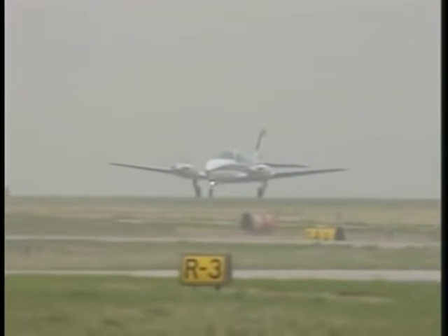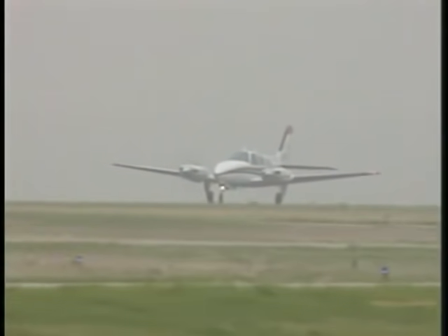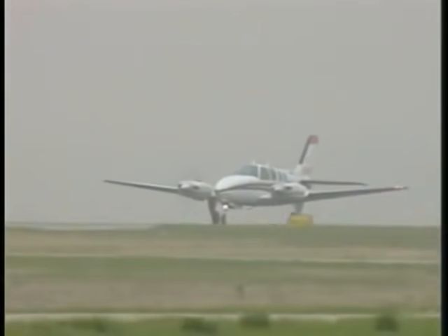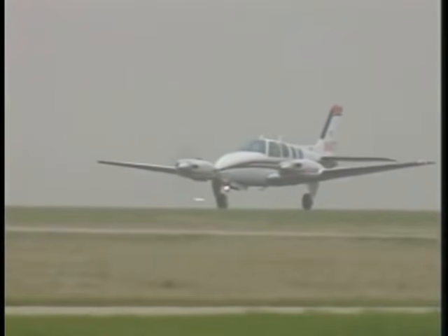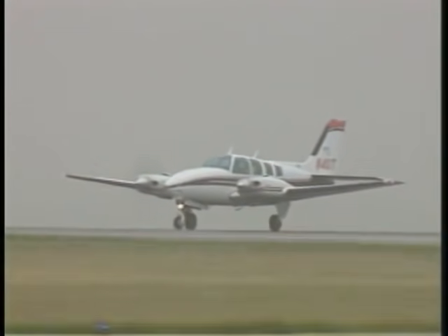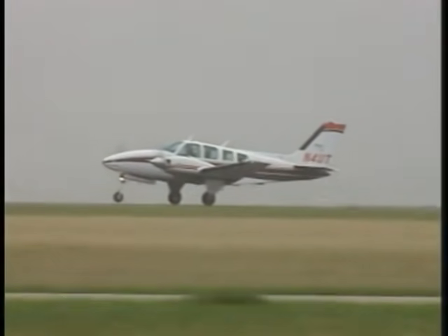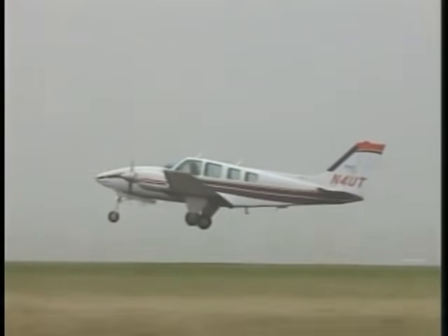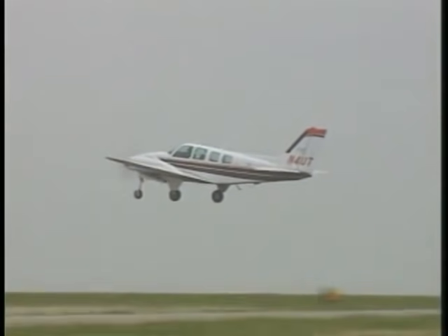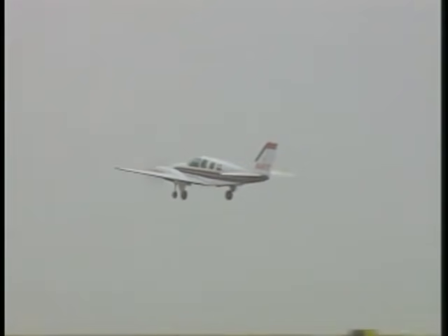The departure procedure you use during an IFR flight varies from airport to airport. Sometimes it may be as simple as a climbing turn to your intended course. At other times, it may involve a complicated set of courses, altitudes, and vectors. Therefore, before making an IFR departure, you should acquaint yourself with the procedures which are available at your airport.